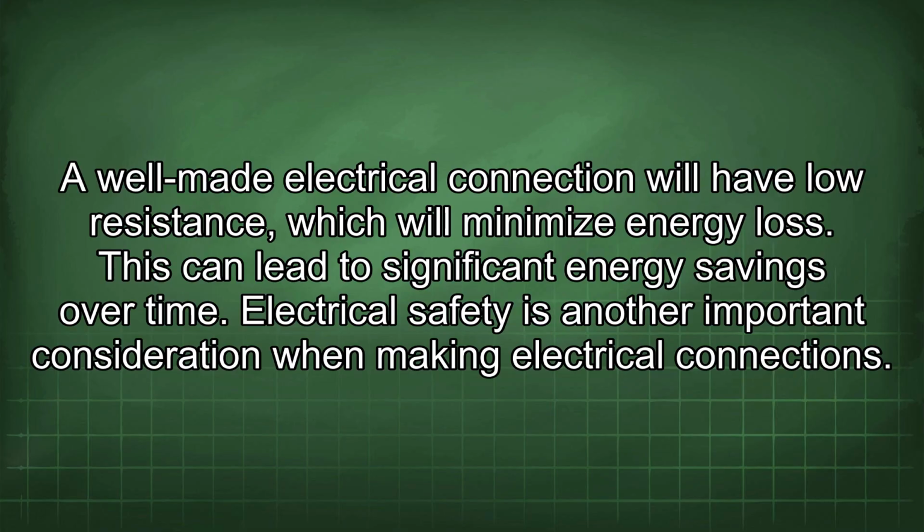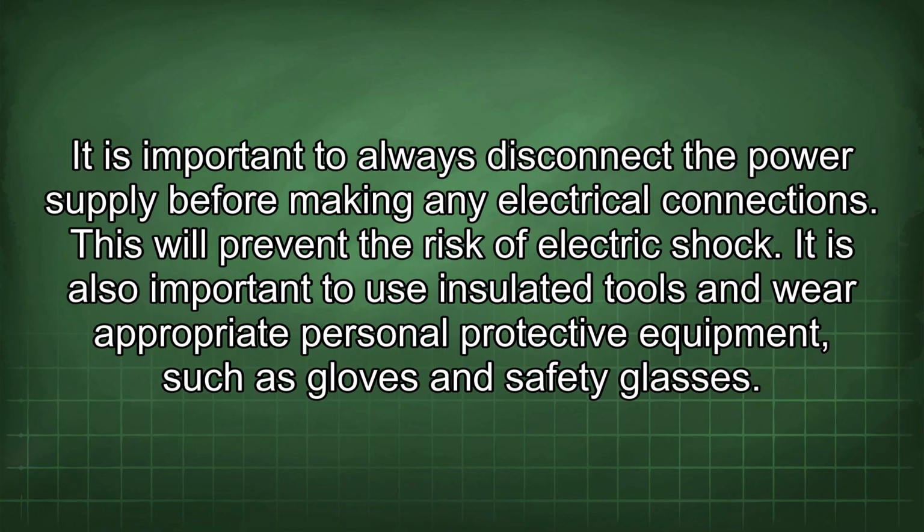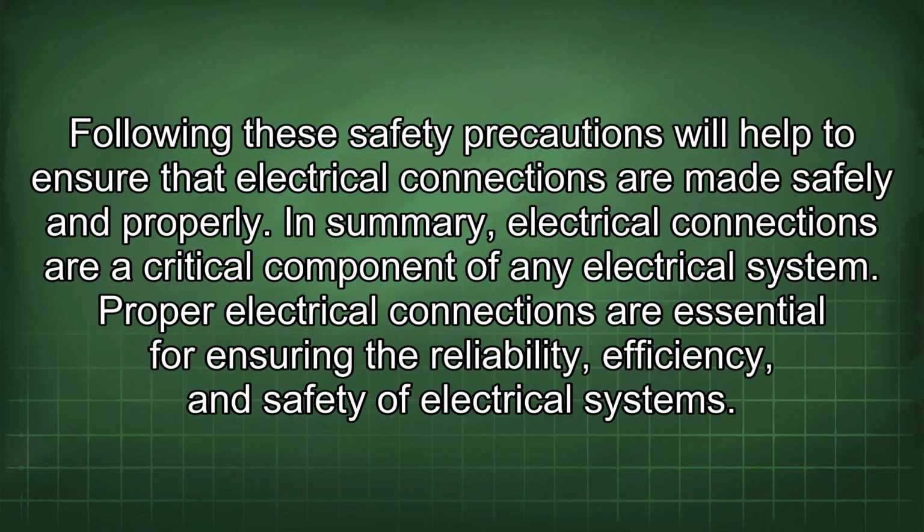Electrical safety is another important consideration when making electrical connections. It is important to always disconnect the power supply before making any electrical connections. This will prevent the risk of electric shock. It is also important to use insulated tools and wear appropriate personal protective equipment, such as gloves and safety glasses. Following these safety precautions will help to ensure that electrical connections are made safely and properly.